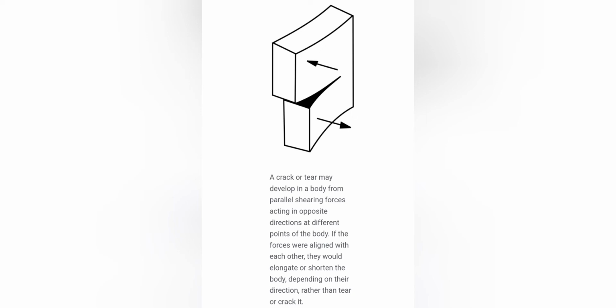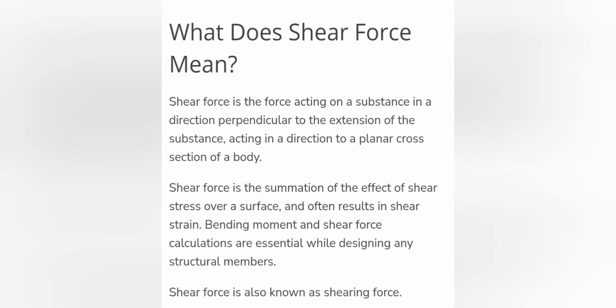Now let's see how shear forces vary along a concrete beam loaded with uniform load W supported on points A and B. If we write the equilibrium equations along vertical direction, we will get the support reactions VA and VB as WL by 2. If we want the force at center of the beam C, by assuming half of the beam, we get zero reaction at the point C, as VA will cancel out WL by 2. By this information, we can draw a shear force diagram with VA and VB at extremes